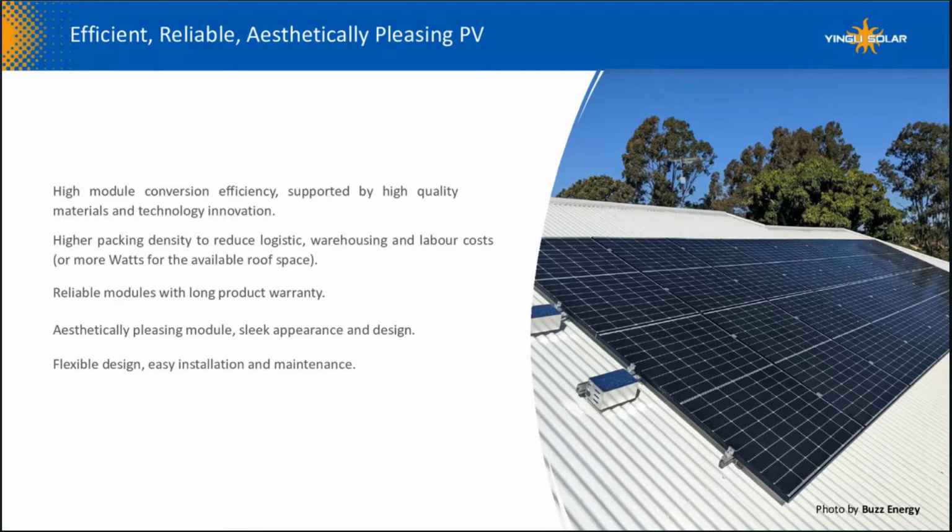In fact, these higher energy dense modules can save you time on a roof, which is not only cost saving, but also a safety advantage. The less time you're on a roof, the less exposure you have to safety issues and or even weather events disrupting your installation. There are also cost savings for the balance of system, and if you can avoid using another roof orientation, thanks to higher density modules, you could possibly avoid the time and expense of extra edge protection.